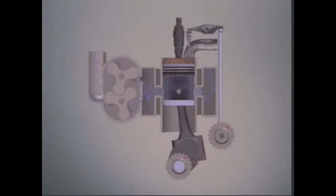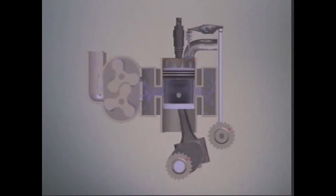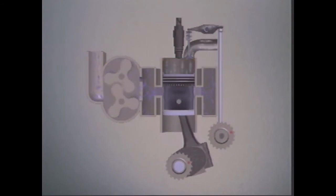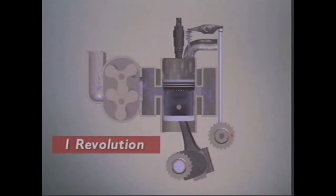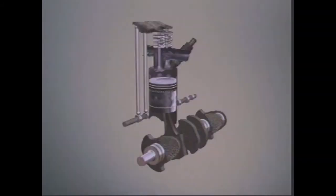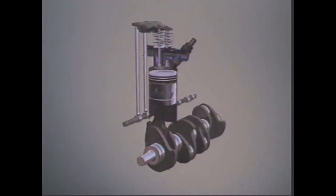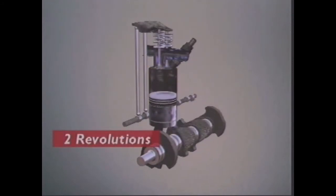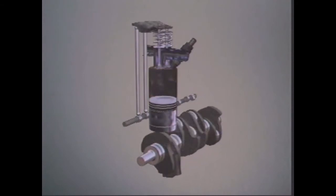The position of the piston is just as crucial in this two-stroke diesel engine. Its exhaust valve must open and close at the right point in the engine cycle. In one two-stroke engine cycle, the crankshaft makes one revolution. How does this compare with a four-stroke engine cycle? How many revolutions does its crankshaft complete from intake through compression, ignition and power to exhaust? It makes 2 revolutions. In that time, what happens to the valves? They open and close once.